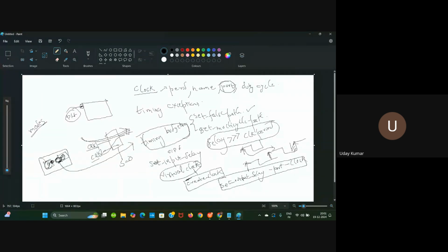These are all called timing constraints. Also, while the tool is optimizing something, it might exceed in some aspects, that is transition, capacitance and delay. So you will have to set a maximum limit. You will give a constraint like, please do not cross this particular value while you're optimizing. The tool can cross it. That is called a DRV violation, design rule violation.